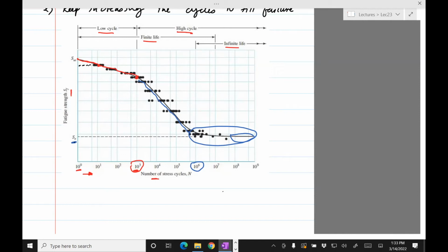So this is just one part. This test over and over. This curve explains for all the cycles. So let's say that you took steel, and let's say this is the curve for steel. It basically tells you that if aluminum is a better example, aluminum is used for lightweight structures. So let's say that you're using it for some machine parts where it's going to be fluctuating load. And then you know that it's going to be subjected to a stress of so much. So that you know, okay, that's going to fail maybe at 5 times 10 raised to 4.